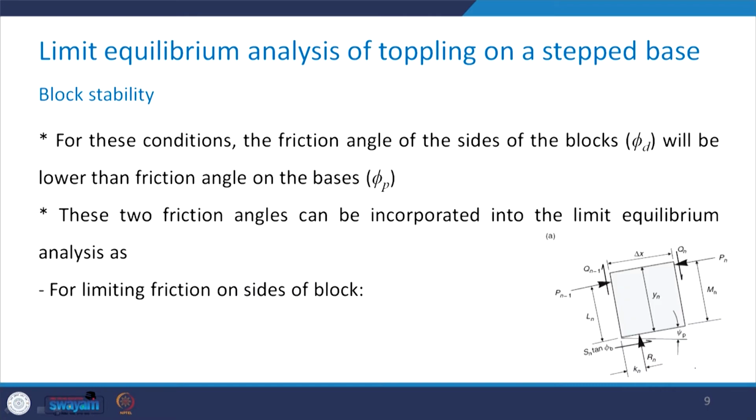For such conditions, the friction angle of the sides of the blocks is represented by phi d. This will be lower than the friction angle on the base, which is phi p. Now, these two friction angles can be incorporated into the limit equilibrium analysis, as we are going to discuss.